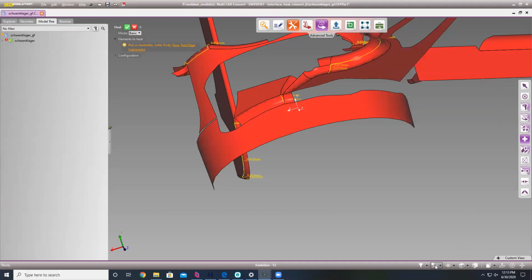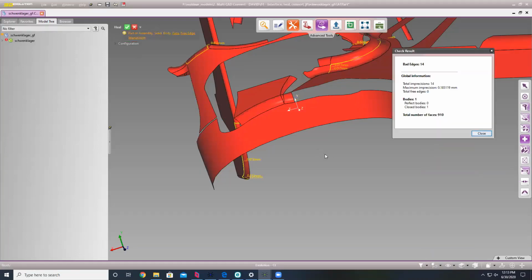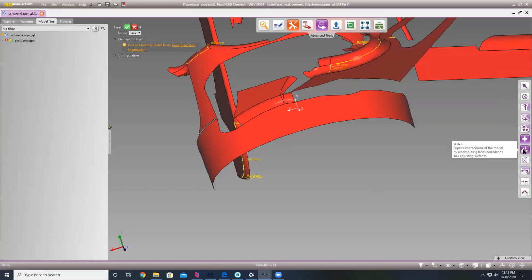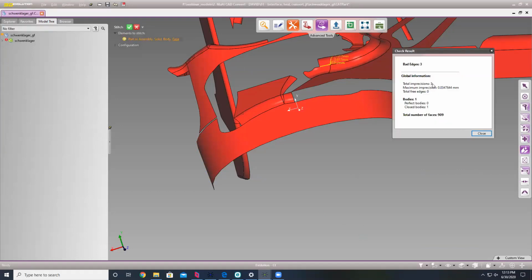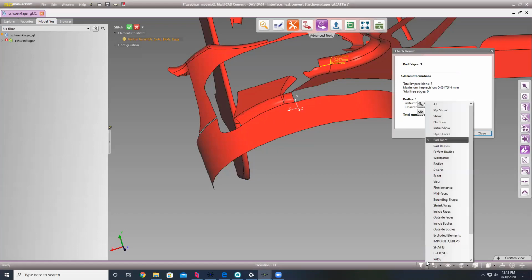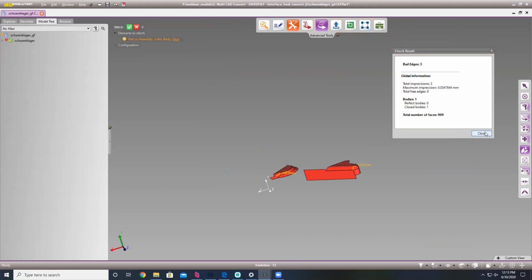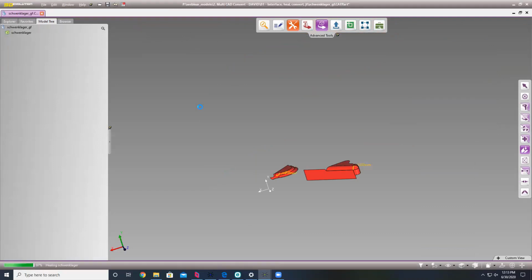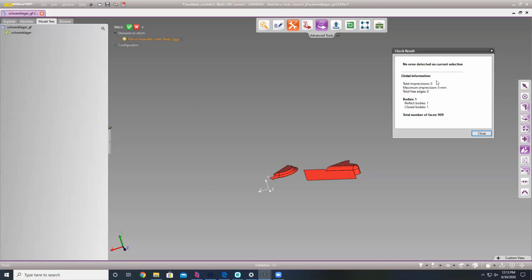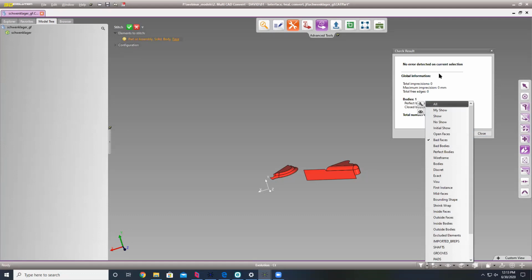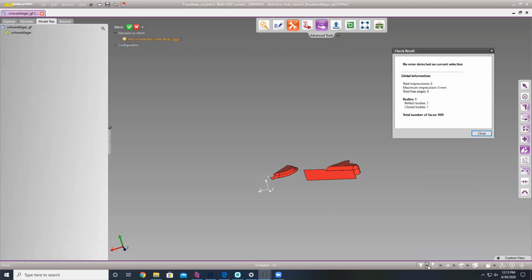And so we're going to take the second action that we took and stitch the model. So it went through now and there's 4 or 3 bad edges. Now, why do those bad edges still exist? You think to yourself it would be fixed, but the word tolerance is a big thing in the industry. And so you have to make sure that your tolerances are set in your system. But now you have a 100% clean face and clean model.